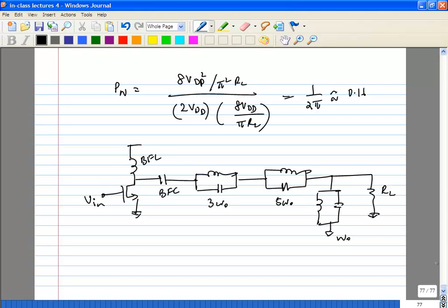The one thing you have to remember is, in all cases your output voltages are all functions of the VDD, so they are actually constant envelope PAs. So they are very good with phase modulation. In cases where you have GMSK or PSK, something like that, they'll perform very well. Now there are obviously extensions to this. If you want to perform amplitude modulation also, people tend to use these because they are still very high efficiency.